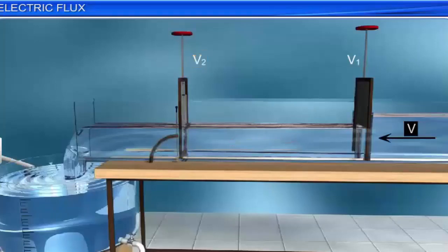This completes the apparatus. Now for the experiment. Keep the area of the opening in both the valves the same. That is, the bottom line of the closing plate in the two valves should be at the same height. Measure discharge Q1 for 5 minutes by collecting the water in the measuring jar. Keep this measuring jar away from the downstream flow.